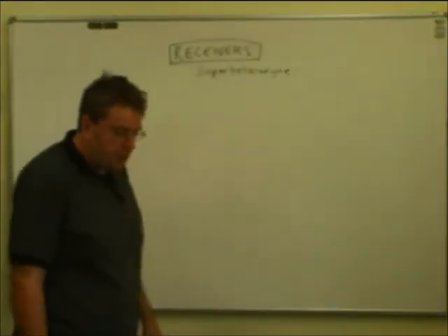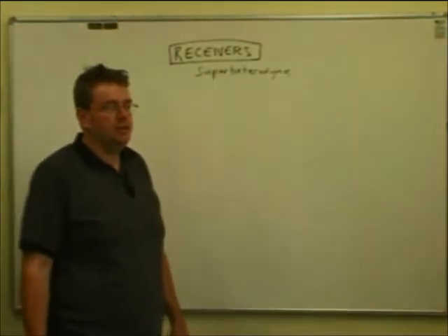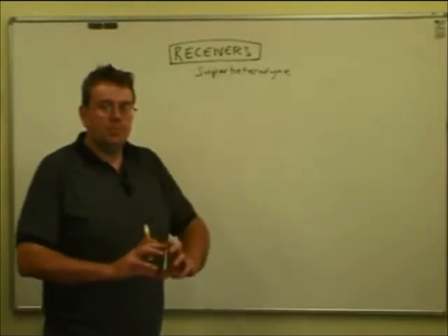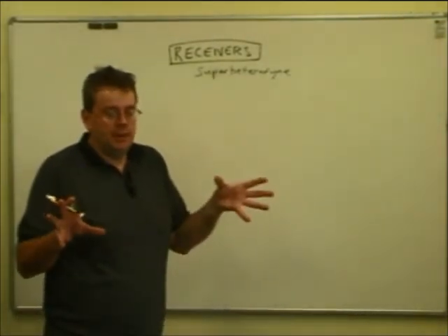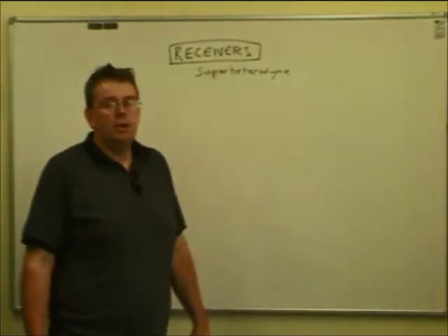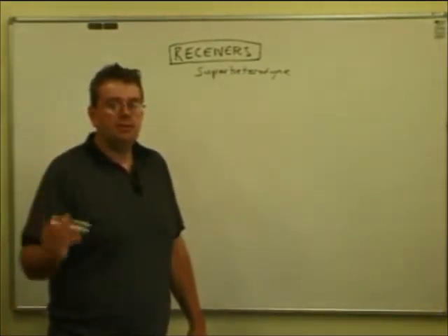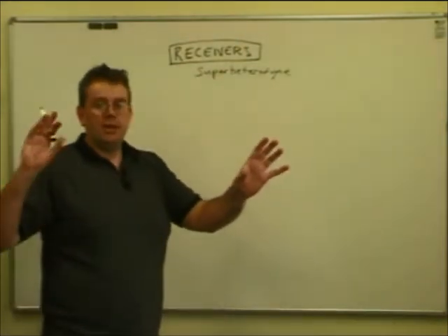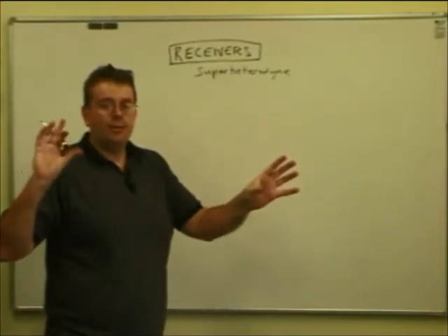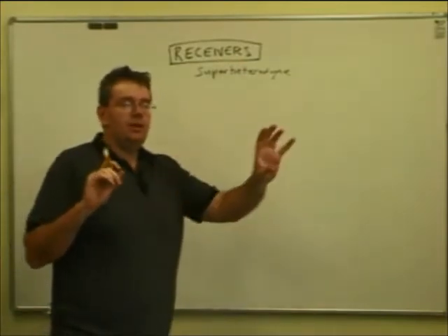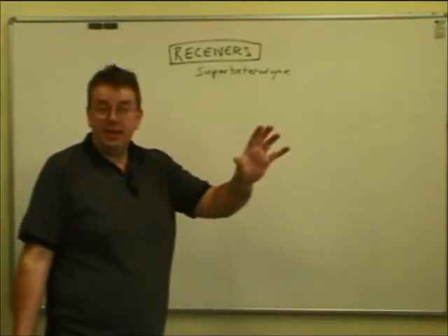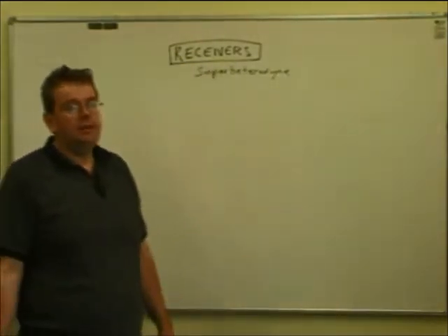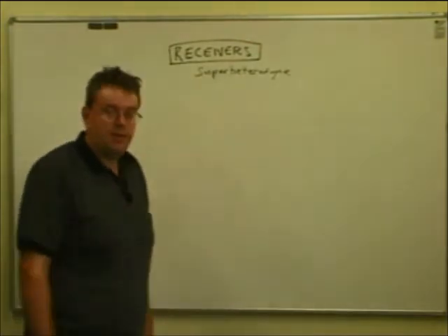The idea of the superheterodyne receiver was to have a lot of amplification in your receiver, but to do it at one fixed frequency where all those tuned circuits could be preset to give a nice selective receiver, but shift the frequency we want to receive to that frequency, and we call that an intermediate frequency. So we receive our signal we want, which you often call the RF, the radio frequency, and then we shift it to the IF, the intermediate frequency, which can be anything. It can be quite low, a few tens of kilohertz, and some receivers right up to quite high, maybe 70 megahertz or so in that Yaesu set I showed you before.